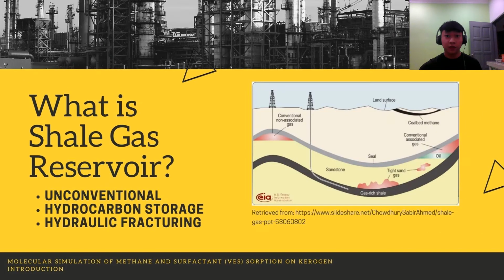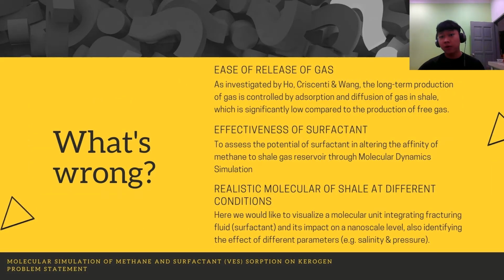First of all, for introduction, the project revolves around shale gas reservoir as we are trying to relate Kerogen in the bigger picture. The thing we should know about this shale reservoir is that it is an unconventional reservoir. Shale is usually part of the fracturing system, which is the source rock. Here, we're trying to go to shale itself to extract oil and gas as if it is a very good hydrocarbon storage. A process known as hydraulic fracturing will be implemented to frack the shale to create a conduit in order to increase the permeability of shale to extract the oil and gas, as the typical permeability of shale is not that high.